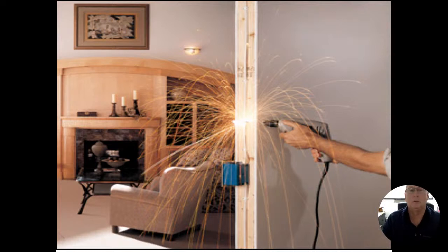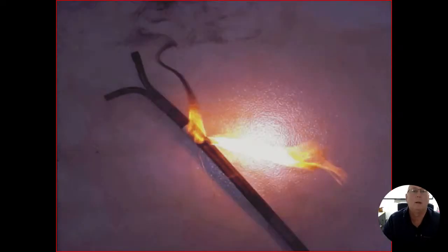This I think is a little excessive. Again, it was this homeowner talking about safety. But if you take something that is grounded, so that drill that he has in there, the bits, everything else, it has a ground plug tied into it. Now he goes into the energized conductor of that wire. You're going to be creating a short circuit and you're going to get sparks flying. All right. Mostly what we're going to end up seeing is the damage of the insulation that comes to it. And that's what we're looking at here.